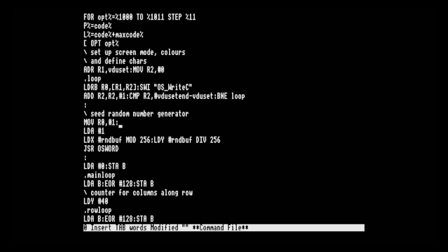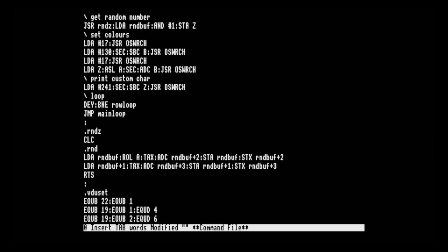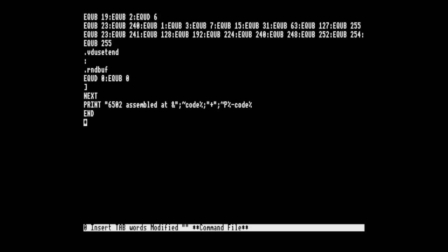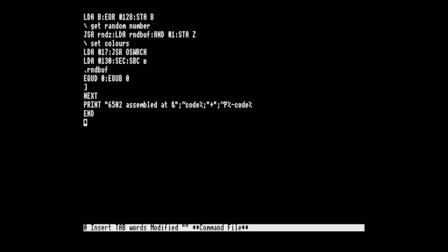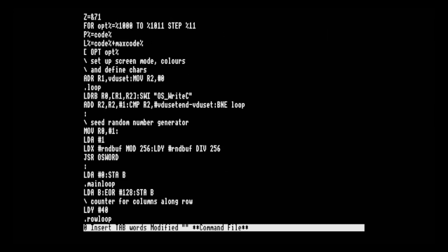Then what we need to do is tell it where's the block of bytes that we want to store the result in, which we allocated at the end of the code here, this run buff thing. So we don't need to mess about splitting the address over 2 registers because all the registers are full 32 bits in size. So what I'm just going to do is say load the address into R1 of run buff.